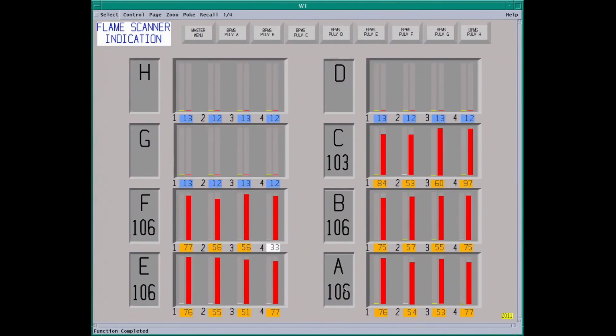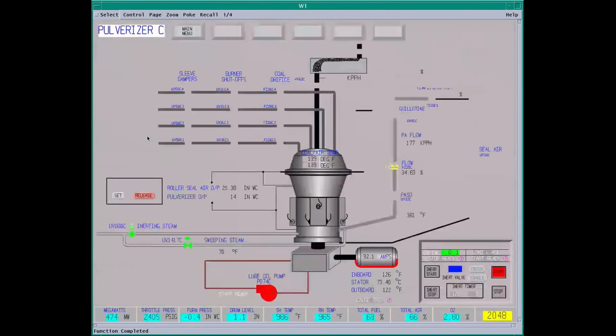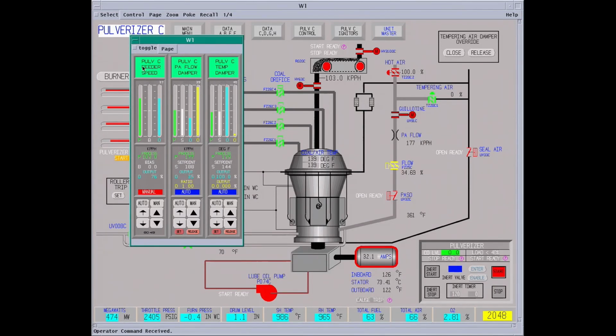Okay, we're almost there. Things around 106. There's 103. As you put fuel on, it automatically backs the other ones down. Same with the igniters. You put igniters on, it backs off the coal feed. The fuel control system works very well. So we're 4,000 pounds off for putting this one back into auto. Okay, from the other screen, they're all equal right now. We can put this in auto.